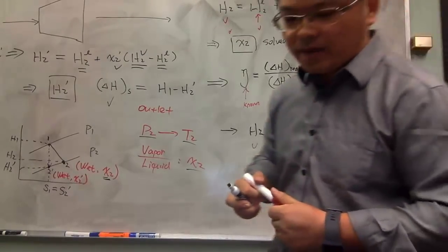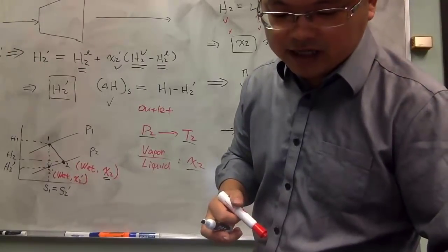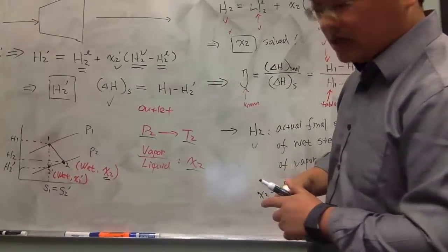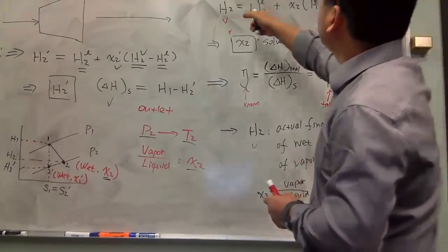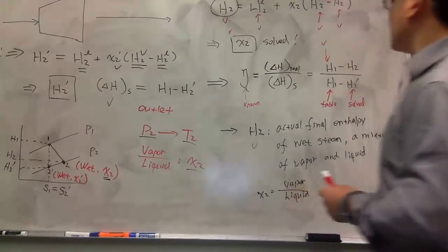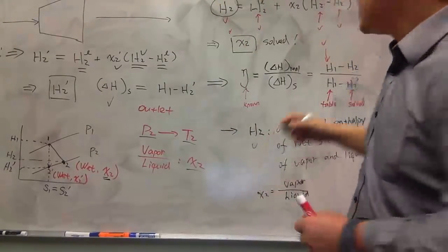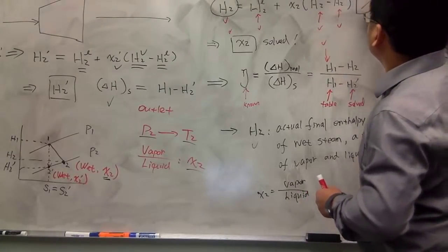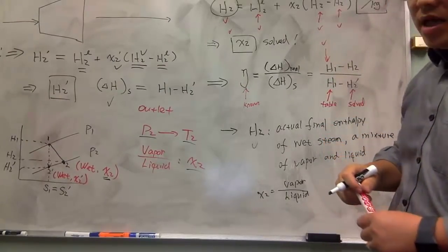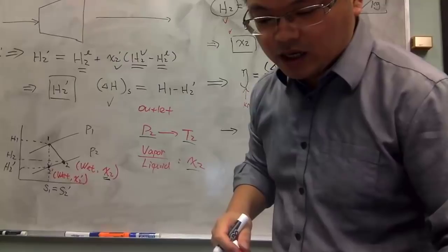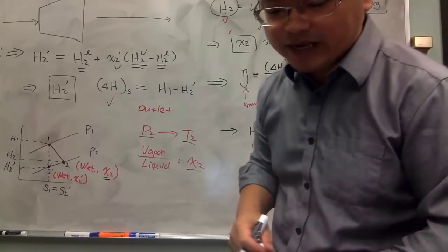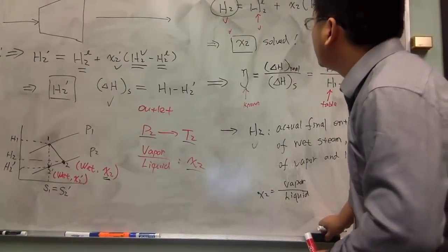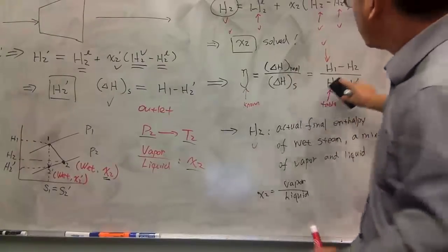The second part is the mass flow rate. Why do we need to have that mass flow rate? This is simply because now if you try to take a closer look at that H2, using the steam table, we are going to use the unit of kilojoule per kilogram. This is the enthalpy unit. However, the requested shaft work is expressed as kilowatt, which is, I'm going to get rid of some part over here.